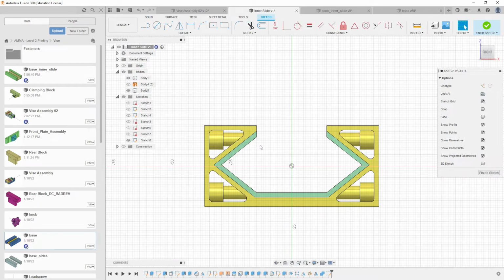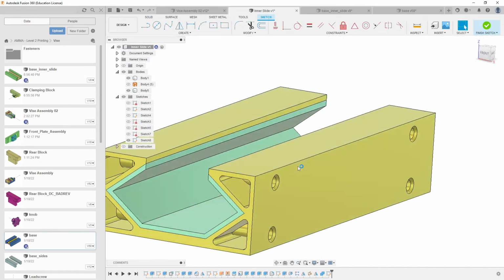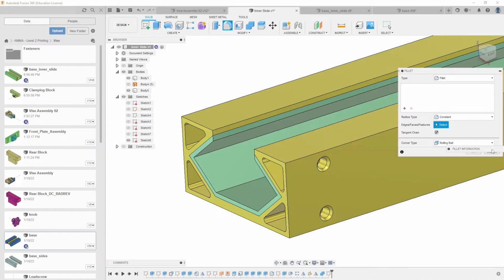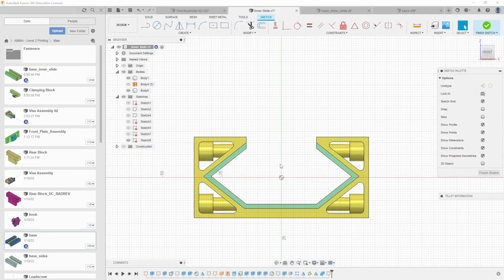And the way visually I'm going to make it the front is, that is not what I wanted to press. I'm going to draw a line from right here straight up. Okay, it's a solid line, so I'm going to click it. I'm going to hit X to make it a construction element. It's not hugely necessary, but I'm doing it.